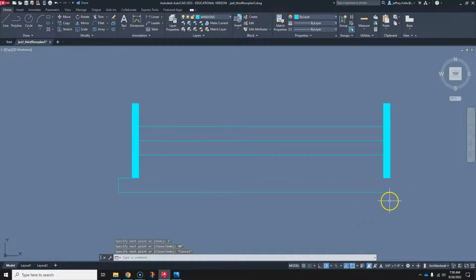And that was not enough. I didn't add that up correctly. Okay, but that's what I was intending to do. So if we've got a 36-inch wide window and I'm adding 2 inches to each side, that should be 40 inches, should it not? Well, actually, too, I forgot to count this 1 inch that I also offset this line. Okay, so that's actually 3 inches I'm adding to each side. So I want to draw this line 42 inches, I think. Let's see how that works. Yes, there we go. Okay.